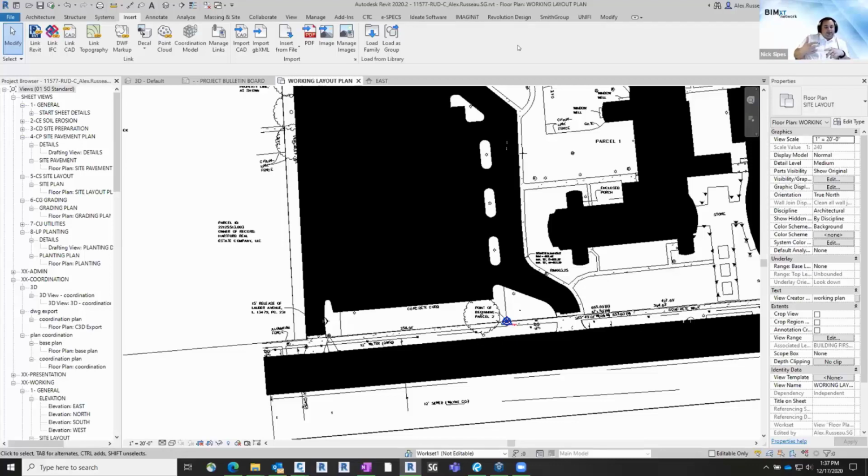And what that does is rather than manually or auto placing it, you can actually pick auto by shared coordinates. And what that'll do is it'll actually align the two coordinate systems between Civil 3D and Revit. And that's how Revit finally learns the true GIS coordinate system. That's the only way that it'll know, hey, it's this NAD 83, whichever state plane it is.